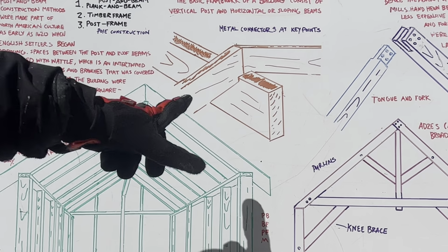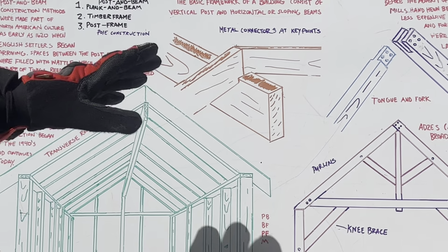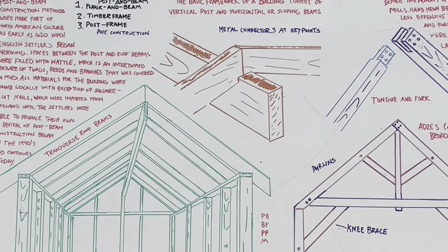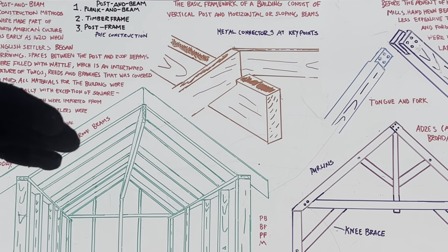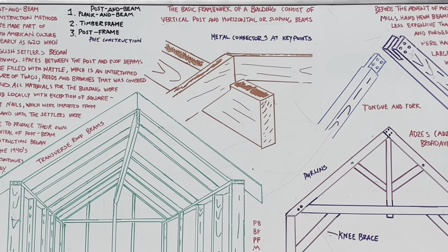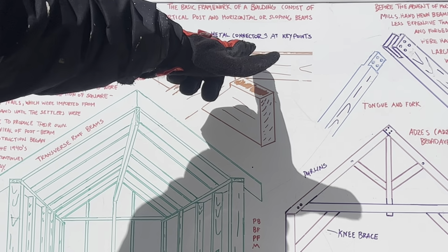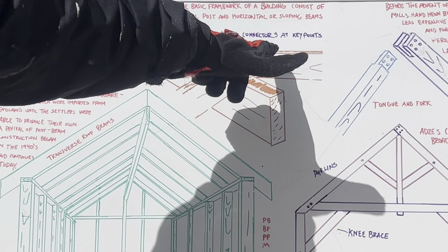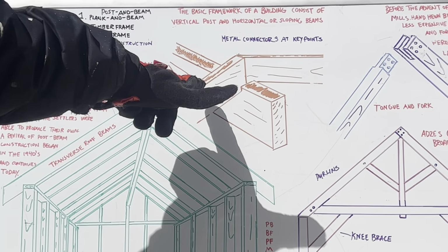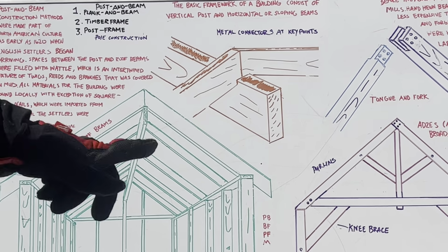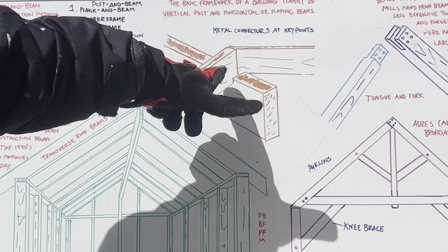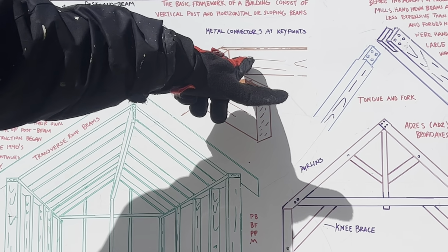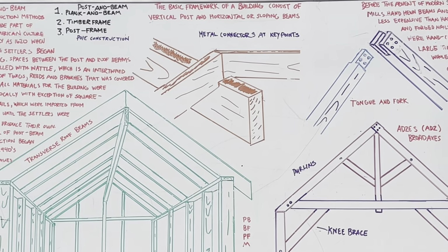That ridge beam. So you'll notch it out right here, and you'll also use metal connectors, okay? Basically at a lot of the key points. So you definitely have either a metal strap right here going along the edge of this beam, or you can put a nailing plate, okay, on this side that's joining the joint, and put one on the other side.